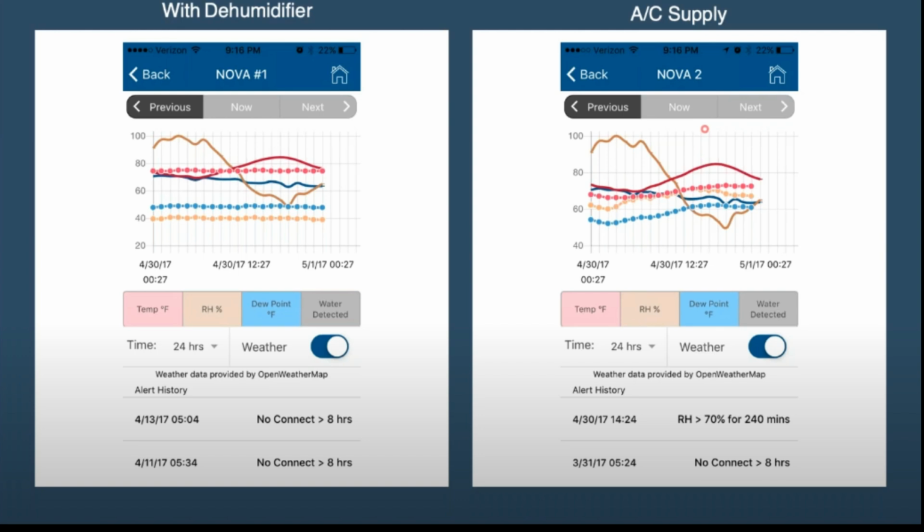You'll also notice the dew point getting above 60 degrees and making the crawl space area conducive for condensation. The RH was consistently getting to that 70% range. Again, if you're counting on supply air to condition the crawl space, the AC has to be running to even push that drier air into the crawl space. This is just not a consistent way to control RH.